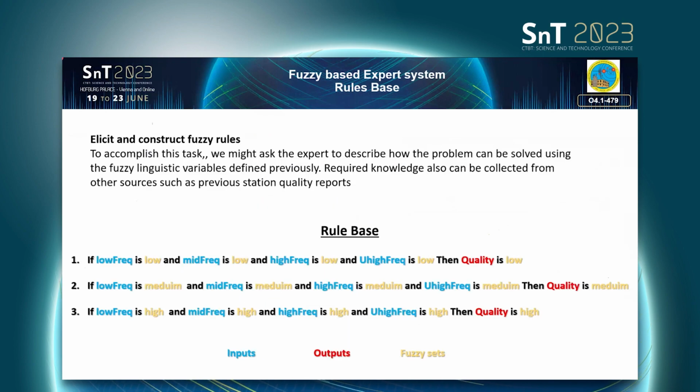The second part of the fuzzy system is the rule base. The rule base consists of many very simple rules that can be expressed by normal English sentences. If-then rules have a relation between the output and all the inputs, or some of them. The most important thing about this rule base is that it can be modified and more rules added as the expert or new information comes, so we can modify the rule base and add more quality parameters as outputs.